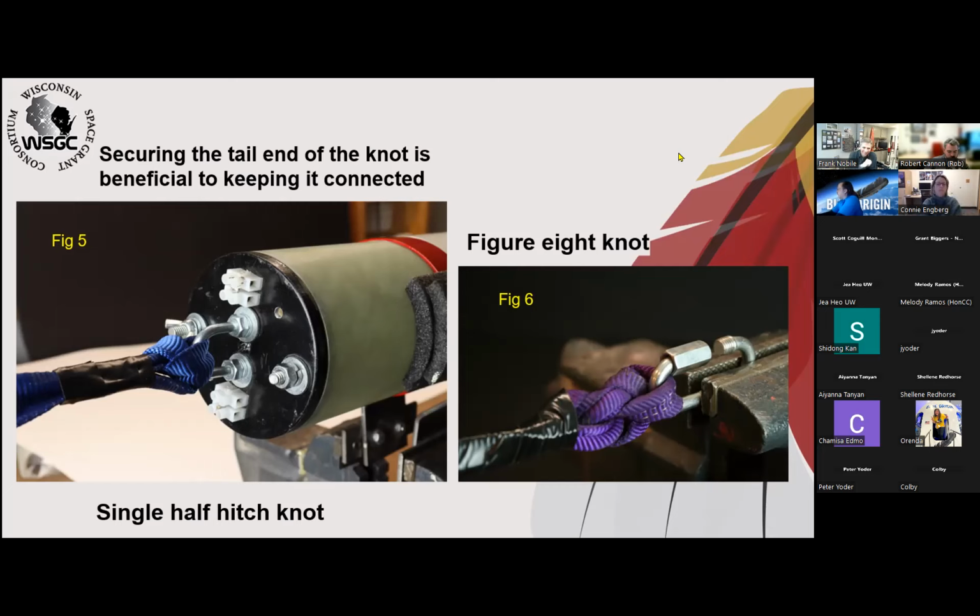Rather than mounting them at 2 points, we're running the shock cord entirely through the avionics bay, and then using cable clamps on the top and bottom to keep it from sliding. Because we've decided to 3D print, to minimize stress points, we've decided to run it completely through and then just hold the av bay in place using cable clamps.